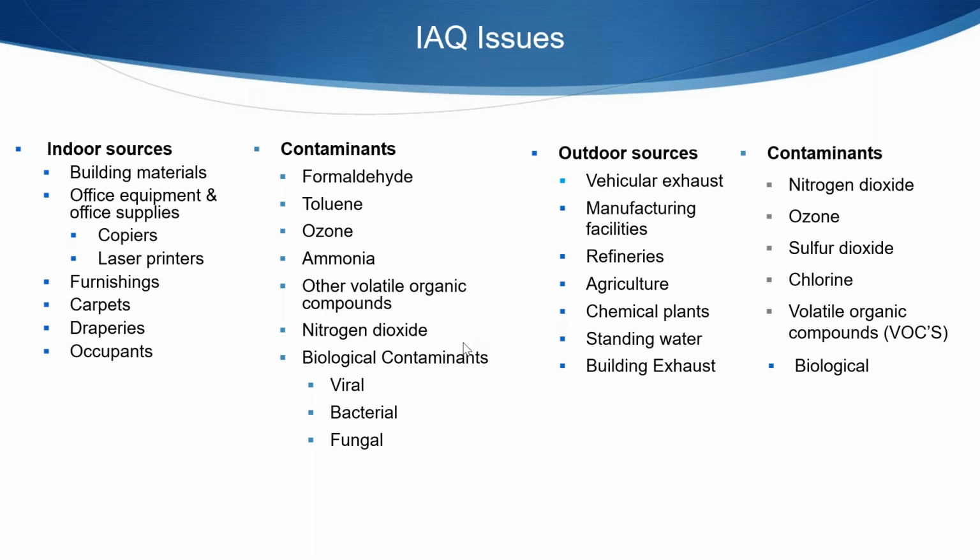There are also outdoor sources that many times we take for granted. "Oh, it's 100% outdoor air, so we don't need to treat for any pathogens." I thought this to be true for a long time also, and I've learned otherwise now. A couple of examples: high density agricultural areas have the risk of consistent contamination from very fine dust and dirt particles being blown in with bacteria on them. I've dealt with some food service clients in that exact situation, with agricultural fields nearby, and they could not figure out why, after replacing their entire HVAC system and even the roof membrane because they thought they had a contamination, they were still getting this specific bacteria. It turned out it was coming in on the wind. So unless they wanted to put up a giant dome, they needed to address it another way. They applied UV to the system and have had great success in providing clean air and eliminating those pathogens.